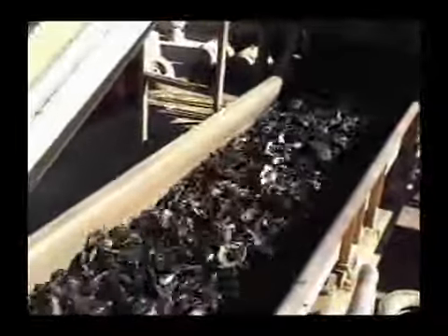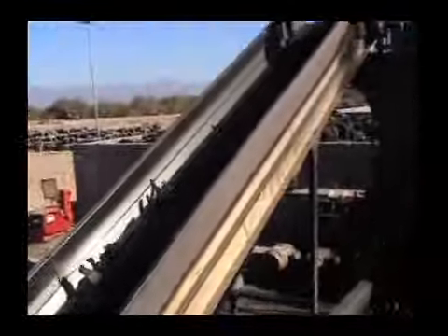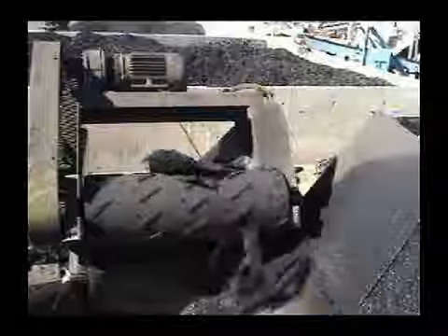Usually shredders run anywhere from 7 to 50 rounds per minute, a slow shredding process. In this department, the whole tire gets shredded down to 2-inch nominal size. However, for different applications, you can take it down to 1-inch or even larger sizes. That's a classification of the tires. It goes to a classification table, and it recirculates back to the shredder until we get to the nominal size of 2-inch we need.